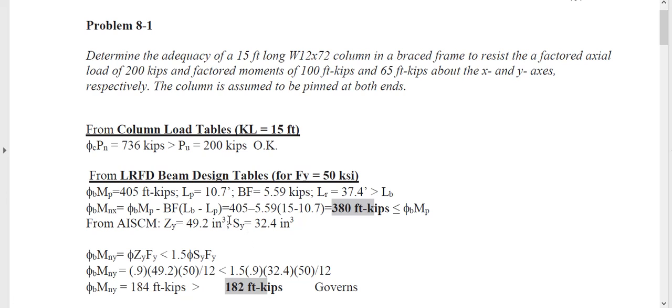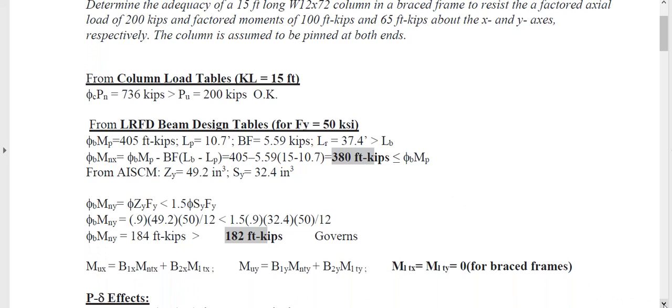Now again, going back here, maybe they made a mistake. There will be a phi here, and they found this value. Yes, in the AISC manual you should get phi BF directly. Whatever you learn, use your own understanding. So that is the only mistake so far I found. It's not a mistake. Maybe in the old version of the AISC they might use this format. Something else also, they did not use Cb here, because mostly we consider it as 1.